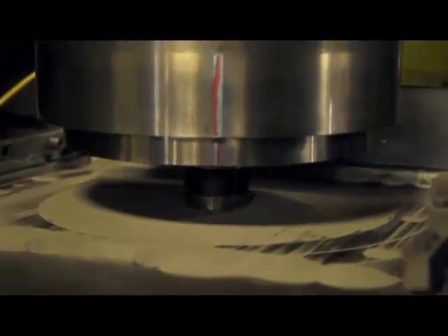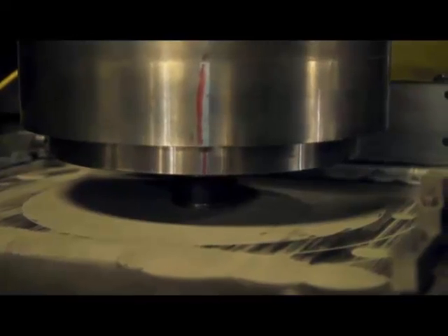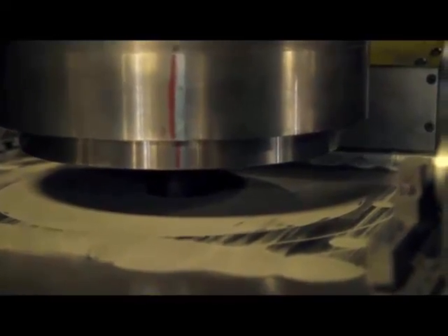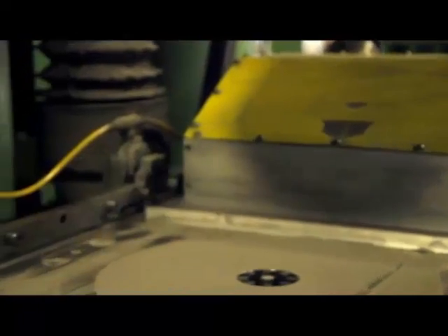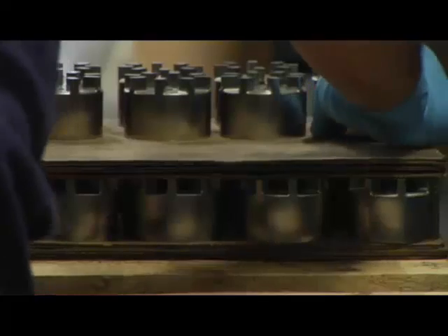During the molding process, the powder is compacted into the desired shape using compressive forces. The part shape is created by compressing the correct blend of materials inside of the part-specific tools. At this stage, the part is considered green and is breakable until sintered.